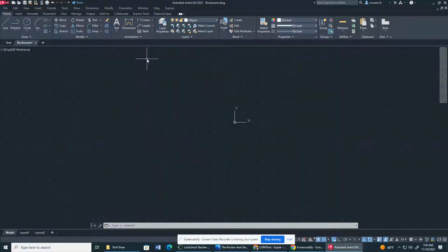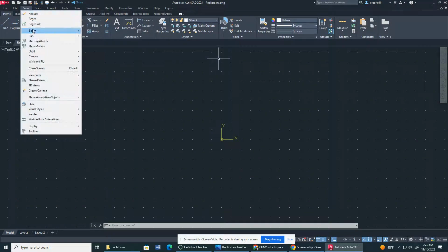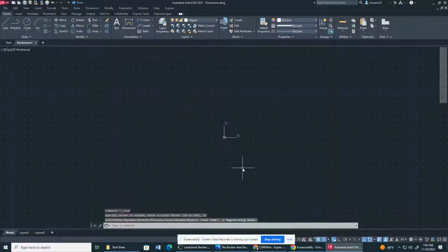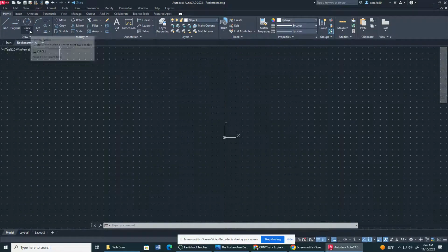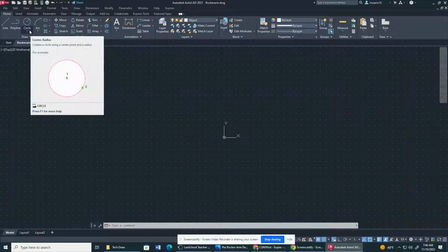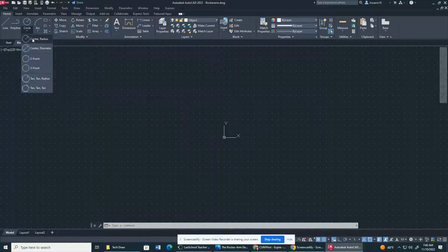Okay. So we're going to start drawing. Let me go back and do that again. Zoom, Extents, right there in the middle. Okay. So right here is going to be 0, 0. So to begin, I make sure I'm in my object layer property. I'm going to go to circle. So for circle, I'm going to set the radius. Make sure we do radius, okay?